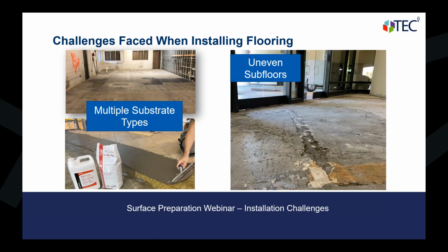On the left side, we have a couple different substrates. If you're doing tile over tile, what kind of materials you would need for that. Here we have our multi-purpose primer and feather edge going over that in order to have a smooth, flat substrate for them to install tile over.